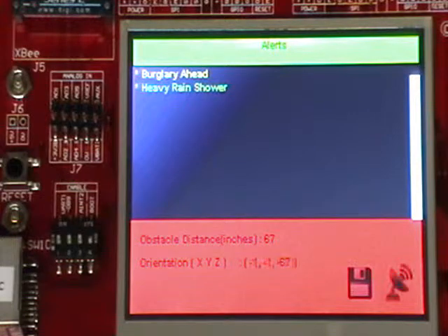Then you have the accelerometer reading, which is pretty sensitive, so it keeps changing, but it's calibrated. Since it is facing in the z direction to the g forces, it's configured for 2g. So you see the z value, the calibrated value for this particular orientation, being 64. It's fluctuating around the 64 value.